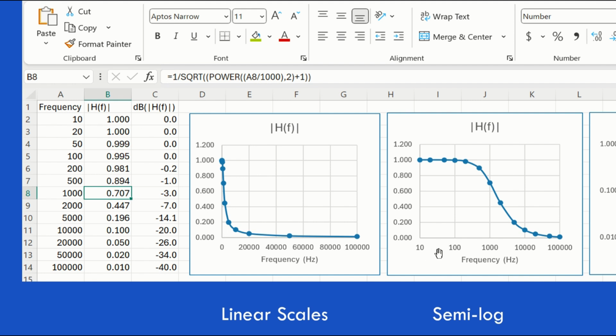But now we, of course, know that we should logarithmically scale the frequency axis. And if I do that, which in Excel involves right-clicking on these numbers here and then selecting log axis, I get this. And what do I see now? Well, I can clearly read off that at 1000 hertz, we're right here, and that's about 0.7, which is what we know it should be. And at 10 kilohertz, I'm here, and that's about the 0.1 that we estimated from before. We still, however, cannot read off a decent value at 100 kilohertz. So what should we do?